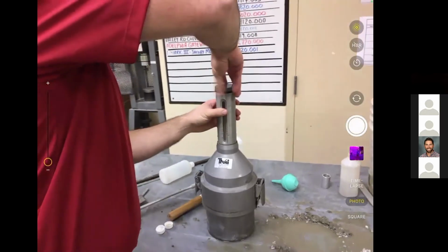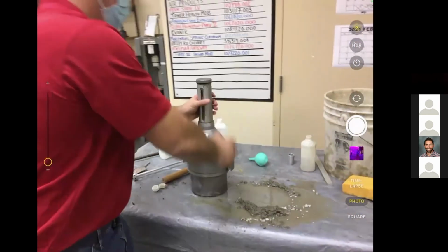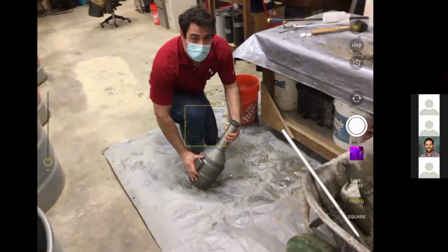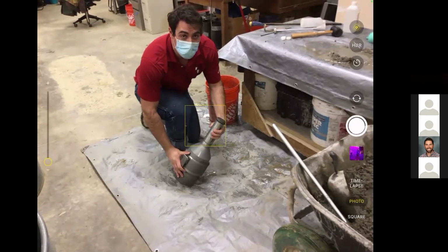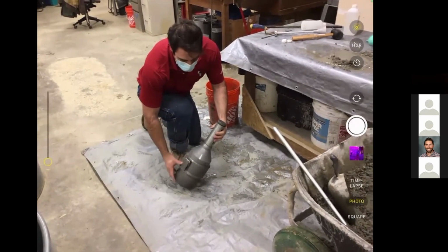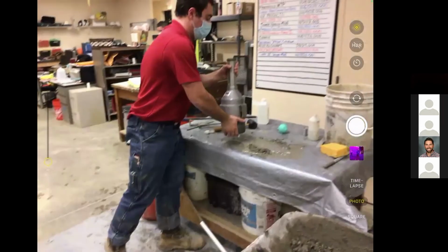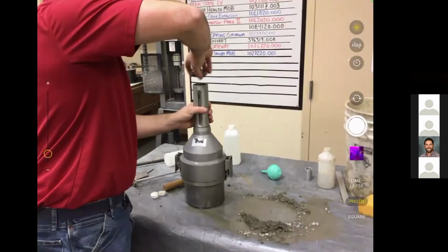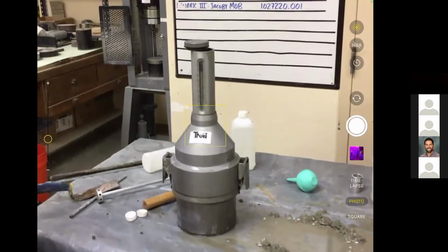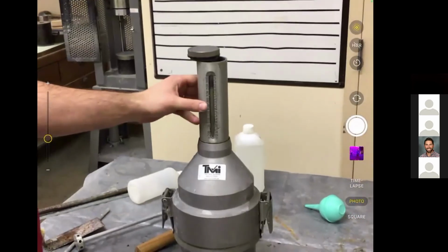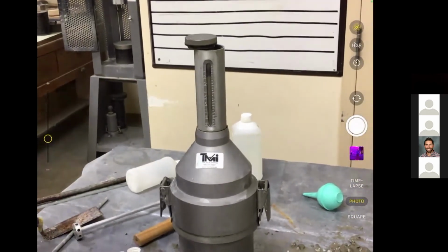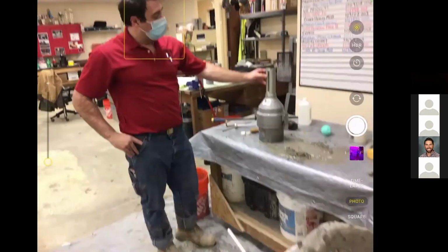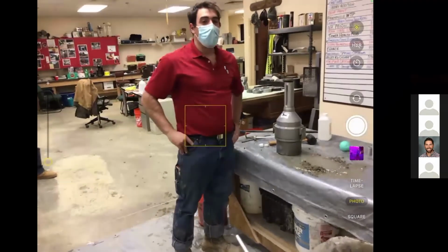We'll put the lid back on, take it back to the floor, and we would repeat our rolling motion, the same thing, 60 seconds of quarter to 1/2 turn rotations. We bring it back up to the table. We would undo our lid. We would wait another 2 minutes to allow the water level to stabilize. If the water level has not changed more than 0.25%, we can take our reading as the final reading. If it has changed more than 0.25%,